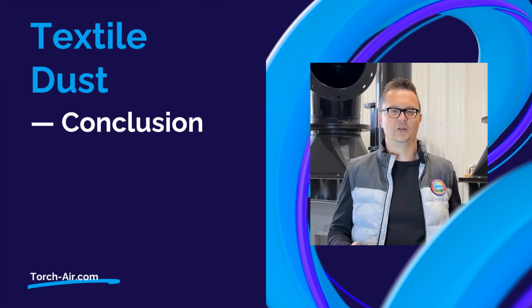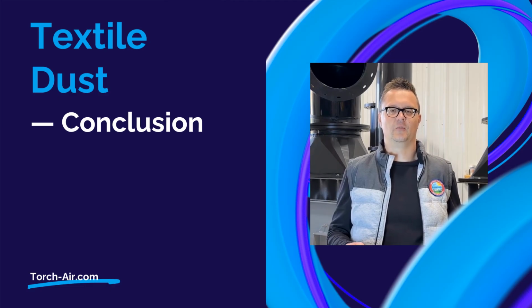Textile dust may look soft and gentle, but it is lightweight, airborne, fibrous, combustible, and capable of traveling everywhere in a facility. With proper airflow, high-efficiency filtration, and well-designed hoods, it can be controlled safely and effectively.